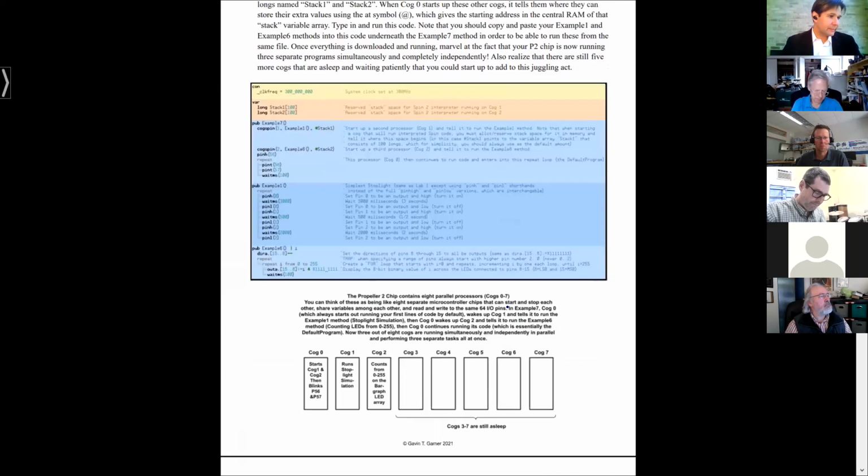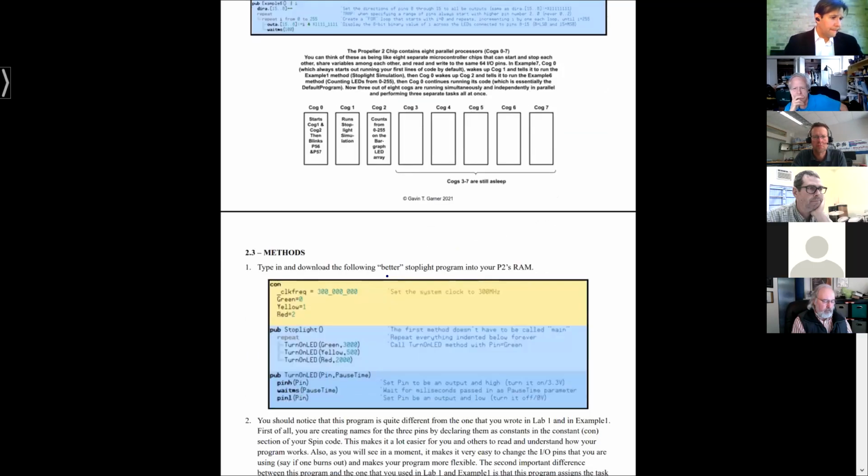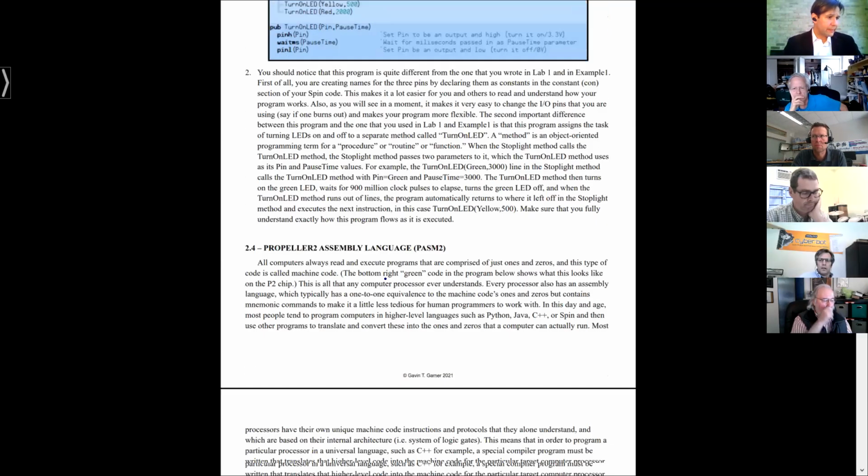And that gets us into the assembly too. So obviously parallel processing sets the Propeller 1 and Propeller 2 apart and is really convenient for mechatronics, where you can dedicate different cogs for different tasks. And that, coupled with the smart pins now, lets you juggle a lot of things at once. So you've got 8 parallel, very powerful CISC-based 32-bit processors. On top of that, you've got 64 smart pins, which are actually little baby processors that can do things like generate PWM signals or analog inputs all on their own. So it's mind-blowing how much this can do at once. Get them into understanding how methods work.